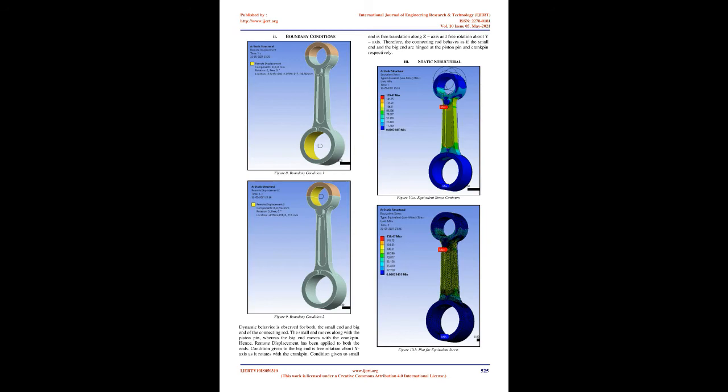Analytical design. Figure 5: Isometric view of con rod. Finite element analysis of connecting rod. Using ANSYS Geometry Design Modeler, the small end was sliced into 2 equal parts. This was done so that the force would be applied only to the lower half of the small end, similar to actual conditions. It can be seen in Fig 6.